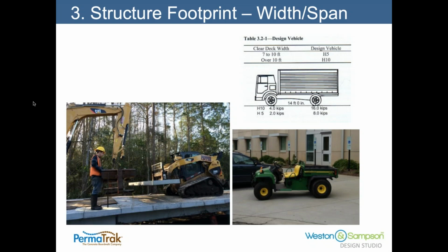And if you look at the structures that are being designed, they are the closest fit to a pedestrian bridge. So you have to go to the Pedestrian Bridge Guide to get guidance on what your design requirements are. So from a structure standpoint, if you're a designer in the crowd, the design vehicle could be, for example, on the bottom right-hand corner, maybe all you want to run over this boardwalk is a maintenance vehicle or a small gator, and the image there may be a 2,000–3,000 pound vehicle. Most people think of running a small gator on the top of the boardwalk.